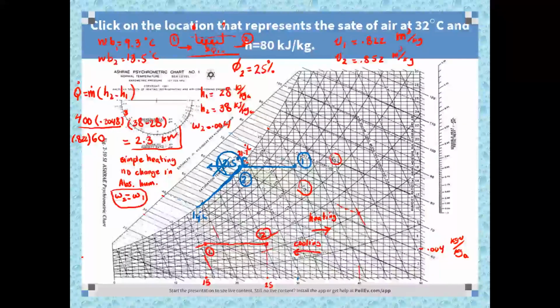So you have cooling and dehumidification. Do we still consider that condensed water as part of the system that gets cooled? Like, does it continue to lose enthalpy? No. The psychrometric chart is for the humid air properties. So once the water is condensed, it's out of the air. Okay. So it is collected in a pan, and it's out of the system. It's not in the air anymore.